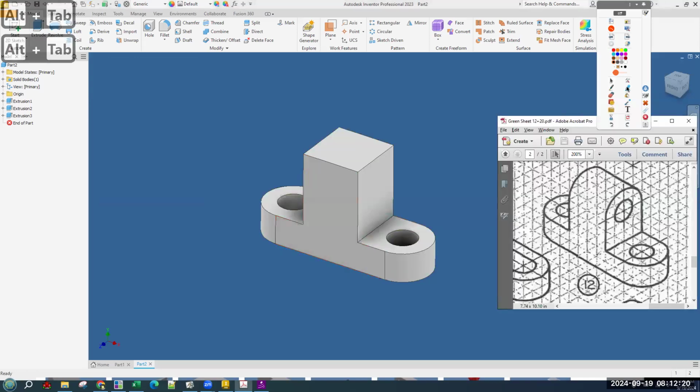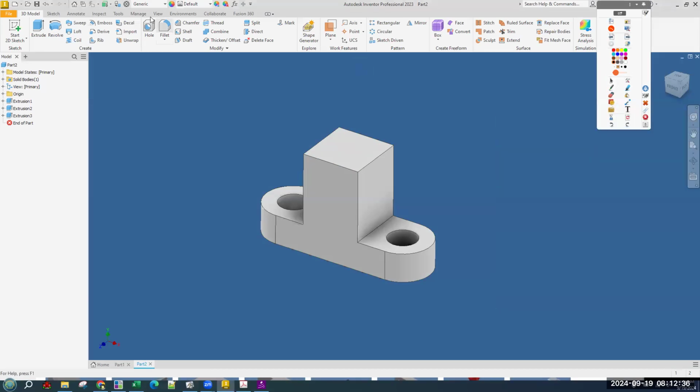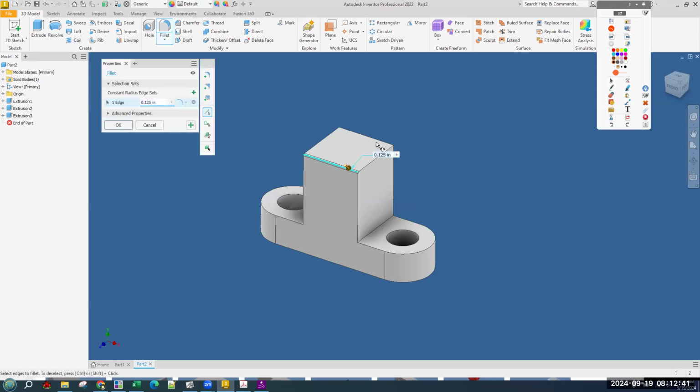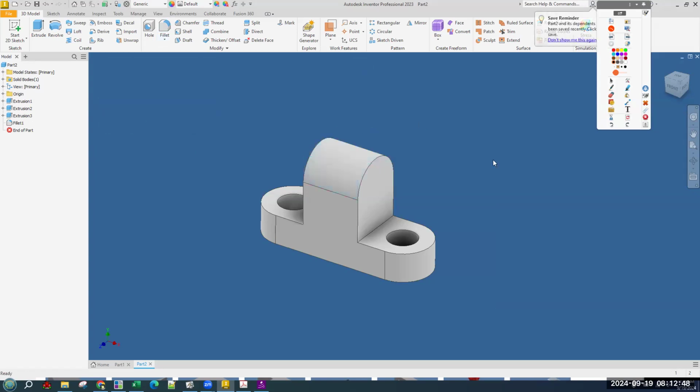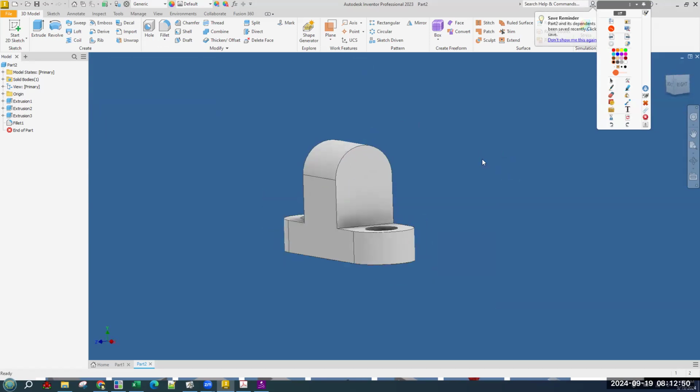And then the shape up here is the same as for number 11. We're just going to fillet this edge and this edge to the right amount so that it makes one smooth arc. And then we just need a center hole and cut all the way through. Okay, so we fillet and choose this and choose that and set the dimension to 2. And there you go.